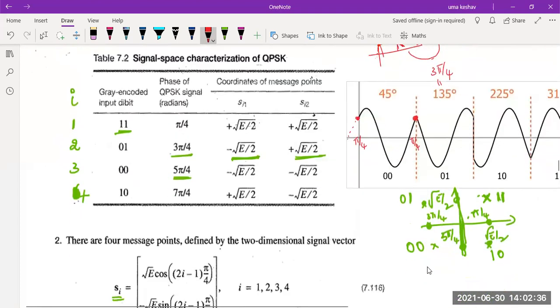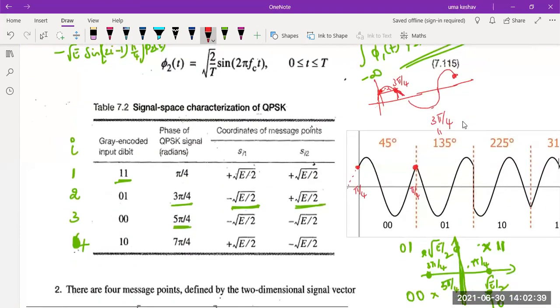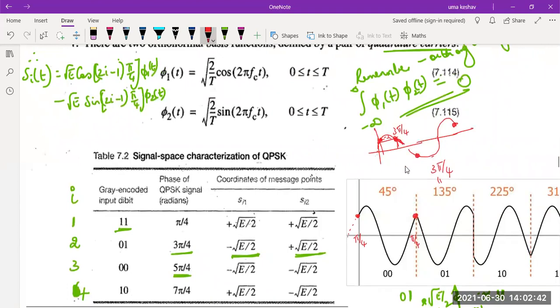Similarly, a 225-degree waveform. You see, where is 225 degrees? This point corresponds to 5 pi by 4 or 225 degrees. So a given waveform should start here, at 225. It should reach the negative maxima, then reach the positive maxima, and again come down and end at the same point. See, the 225-degree lines are the same. Just like how 45 and 135 are the same, 225 and 315 would be the same. Anyway, starting at 225, ending at 225, one cycle.